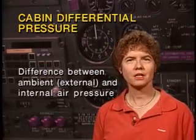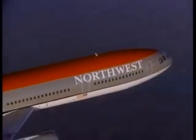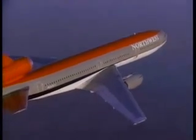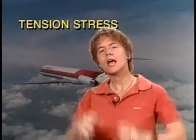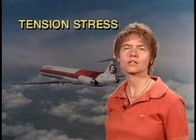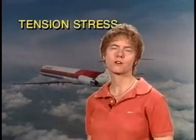Now, when you pressurize an aircraft, you impose stress on that aircraft, and the kind of stress you impose is called tension stress. When that aircraft is pressurized, what you have is higher pressure air inside the aircraft than there is outside in the ambient atmosphere, and it's pressing outward on the fuselage, and that kind of stress is called tension stress. And you can measure how much stress you're putting on the aircraft by how much the cabin differential pressure is. Now, the fuselage is designed to only take a maximum amount of differential pressure because it can only take a certain amount of stress.